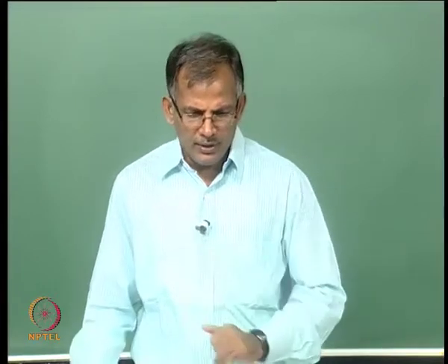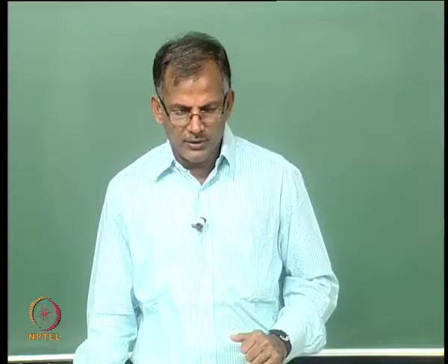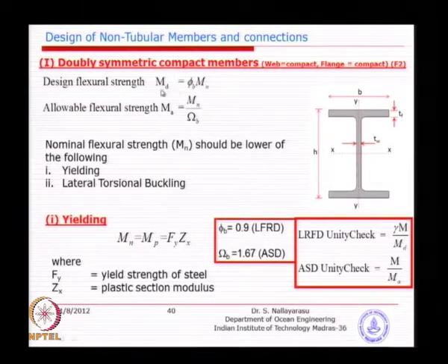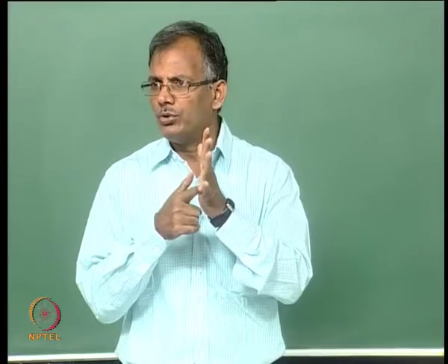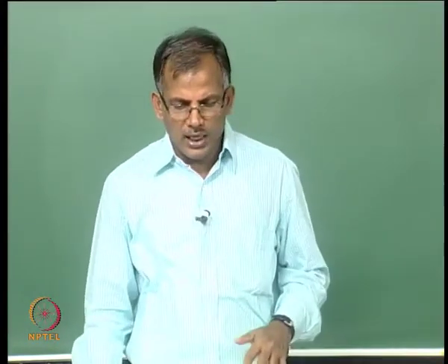If you look here, again a similar idea: allowable flexural strength and design strength. This is for LRFD, this is for allowable stress design, and the nominal strength is given by the yield strength multiplied by the section modulus. So this is where one major difference has been made. As long as you look at IS 800 or any other codes, including the 9th edition of the AISC codes, this has always been